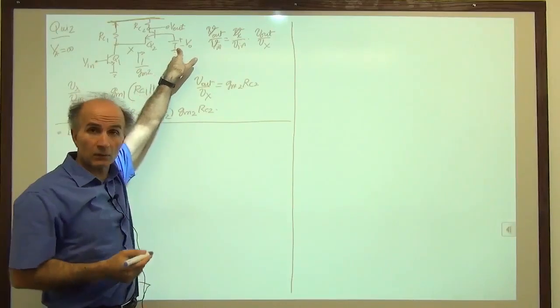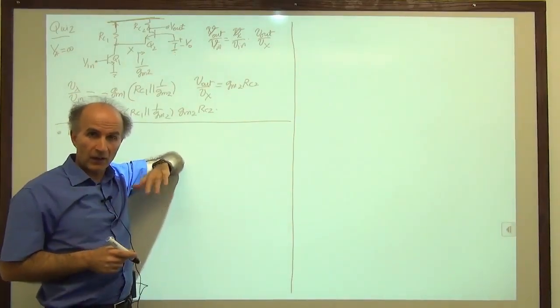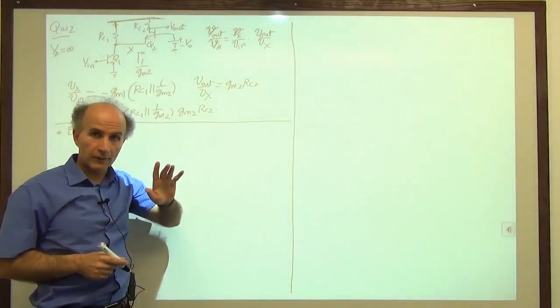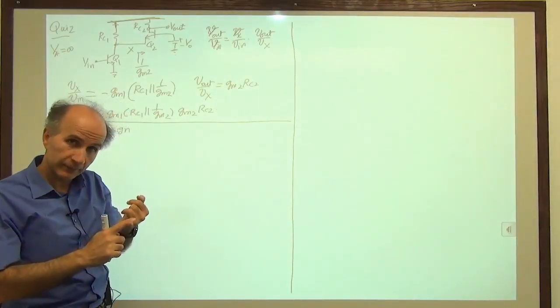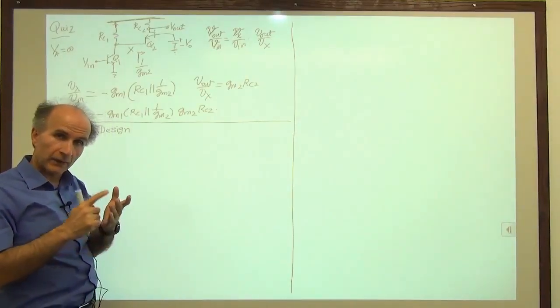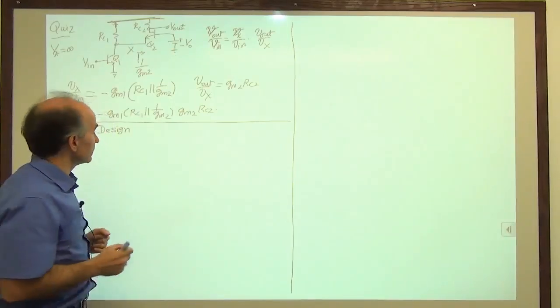There's a battery here, so we need a resistive divider there. Nothing really that new, but we just have to make sure that the transistor, first of all, operates in the forward active region. Second, carries proper collector current. And third, its base is properly biased and all that.